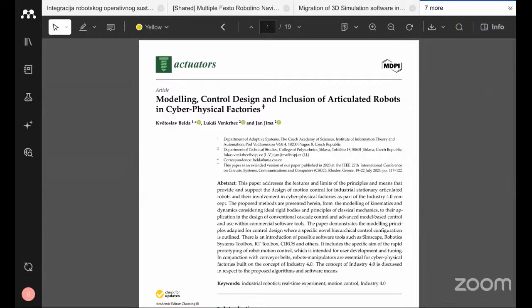For example, in this case, we have the conveyor belt and we have the box, right? So the workpiece is coming through this conveyor belt. We have an RFID sensor, so the sensor will identify the box or the workpiece. Then that message will be communicated to the PLC, or the factory control system. After that, the robot will pick the object and transfer it to the next station. And all this information will be communicated to the central system.